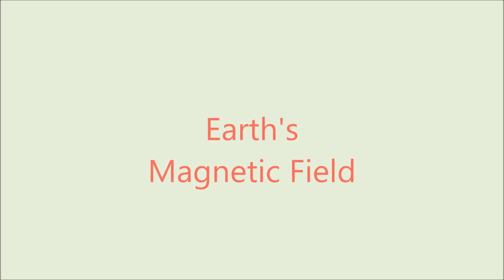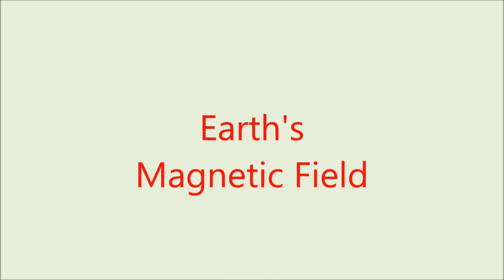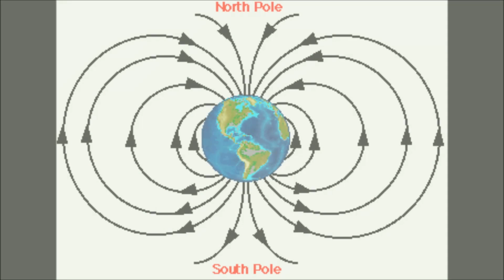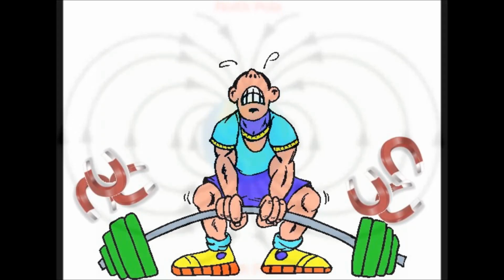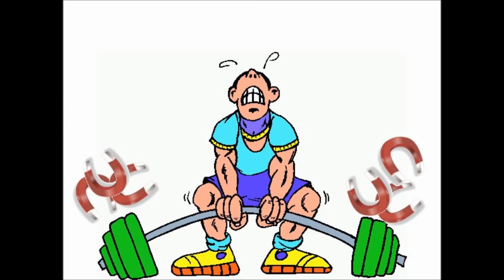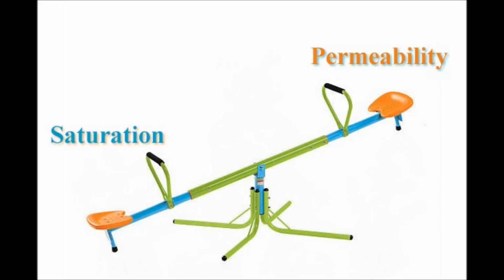The effects of the Earth's magnetic field and other ambient magnetic fields. The omnipresence of the Earth's magnetic field becomes an important factor in shield design when shields are large. Saturation is the instantaneous and reversible process where the shielding material is conducting all the magnetic fields that it can. Additional magnetic fields will not be affected by the presence of the shield. The higher the permeability of the material, the lower the saturation point.